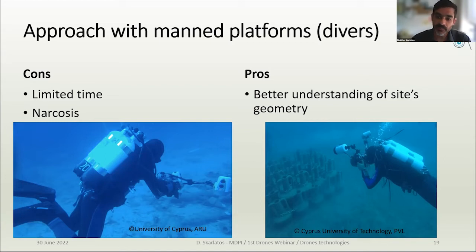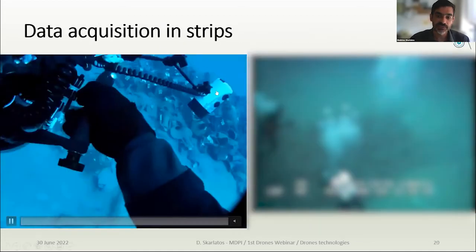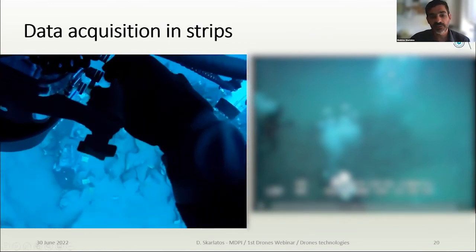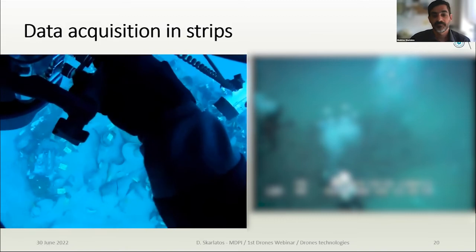On the other hand, the main advantage of a diver who knows photogrammetry and is quite experienced in photogrammetric acquisition is the understanding of the site geometry, which is something you cannot easily have when looking through a monitor with a 90 degree field of view, for example. So using a diver has certain advantages. Then again, you may only use a diver up to 60 meters.